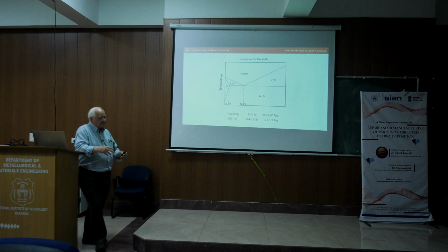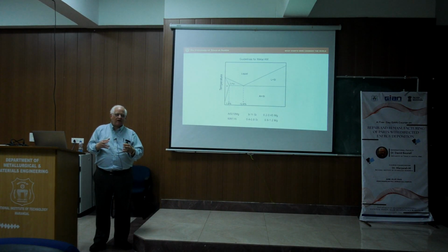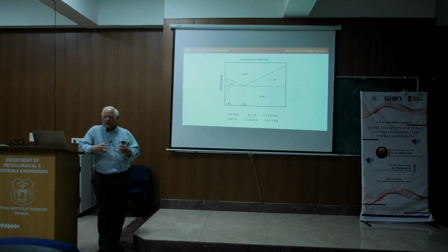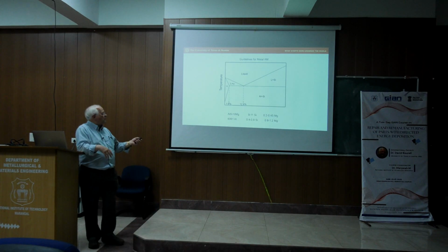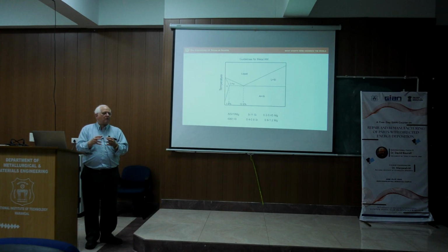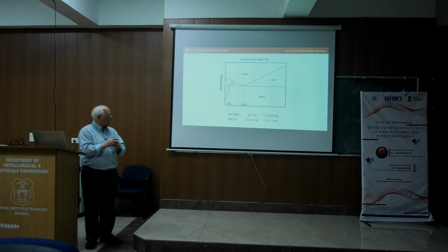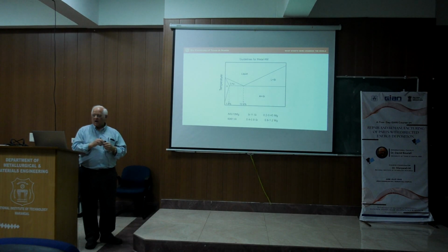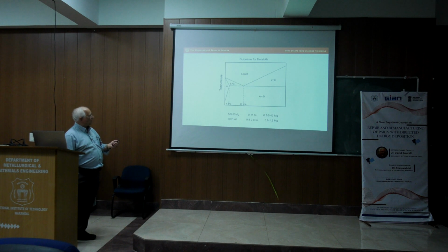And as the solid forms with the cooling temperature, there's shrinkage, and oftentimes these form with a sort of dendritic array, where it's very easy for the liquid to get pinched off from the main body. And when that happens, with further cooling and contraction, we tend to form either porosity or cracks, because as we go from liquid to solid, there's a lot of contraction that occurs.